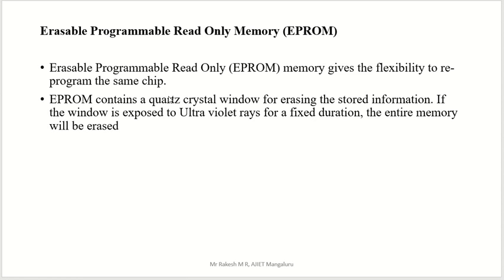We expose the window to ultraviolet rays for a particular amount of time, a fixed duration, then the entire memory will be erased. But this fixed duration is very important. Don't expose the EPROM for more than that fixed duration, as that will lead to problems. This is about EPROM.